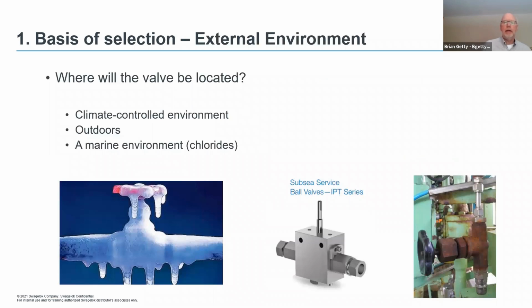Okay, you want to look at the environment where the valve is being installed. Is it being installed in a climate controlled process factory, somewhere where it's at 70 degrees, or is this valve actually being installed outside? Especially here in Quebec with our winters, minus 40, a little less often nowadays, but we do see minus 40s. So you want to make sure your valve is capable of handling that kind of temperature.